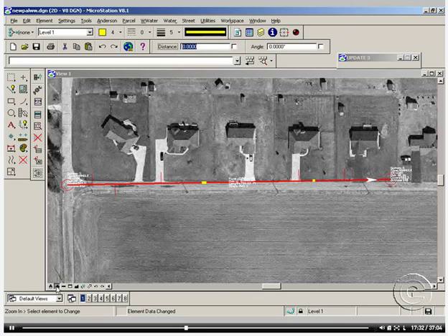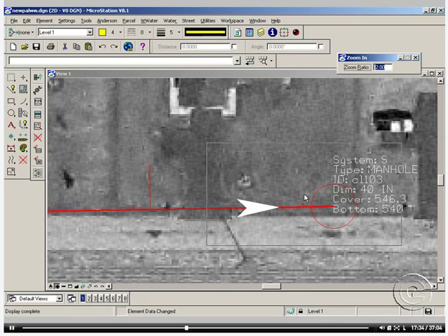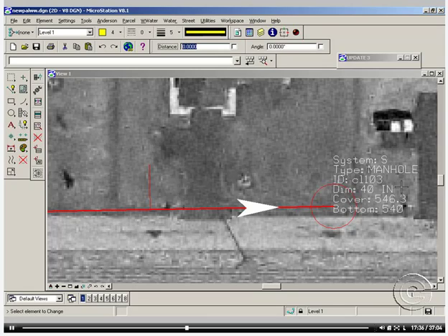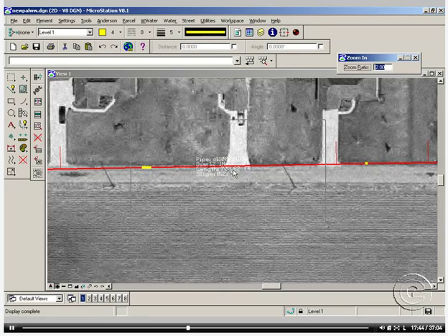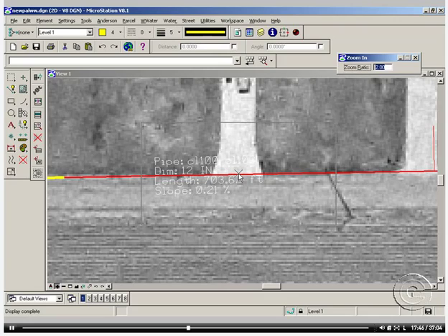And then again, as you would go and zoom in and look at your information, you would see that your information has been updated to reflect the new data that you just entered onto that node. And again, all the pipes and all the laterals to those pipe and observation would also have been changed to reflect that information. For each pipe that is connected to the node, the deltas would change to maintain the slope that we have, because we assume that the invert elevations are still the same on that node. It was just either raised or buried again.